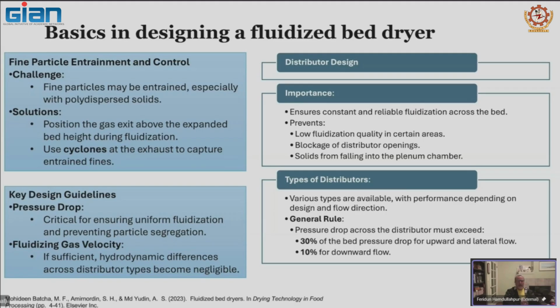I mean, you cannot escape the pressure drop that will be needed for the minimum fluidization. Remember, you need that delta P until you overcome the bed resistance. After that, it is flat. So make sure that you're fluidizing in an efficient way.